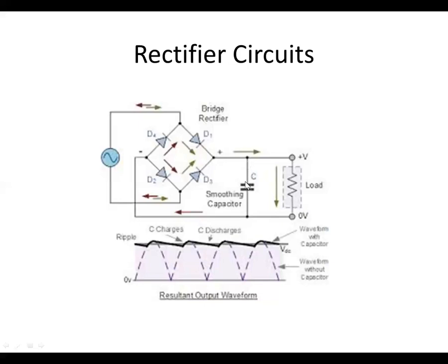And what this does is it will absorb the current flow, build up an electric field in the capacitor, and it'll come up to the peak. So during this part of the cycle, the capacitor will charge, caused by this pulse from the bridge rectifier. And then when the voltage goes below the voltage output of the bridge rectifier, then the capacitor will slowly discharge until the next cycle.